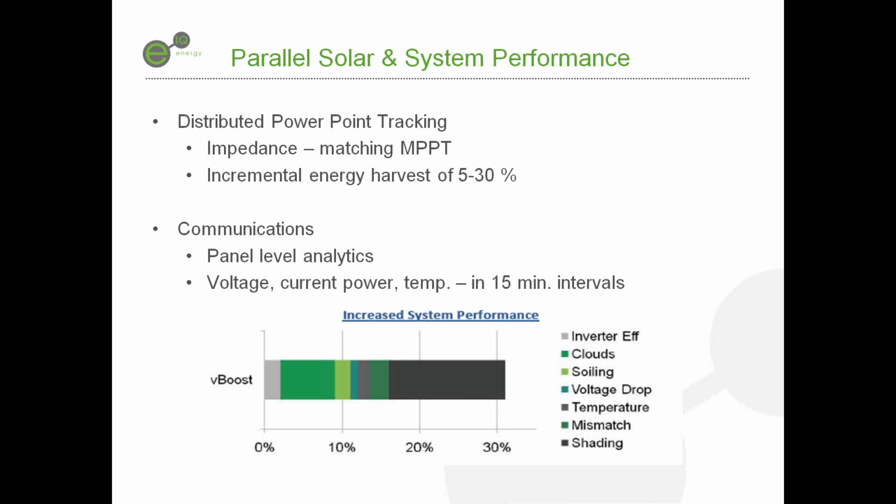And by doing this, you can see here that we're going to get a number of factors that build together in order to get the increased production story. So, for example, there's a couple of points available for inverter efficiency. And what we talk about by that is being able to drive the inverter at a consistent voltage that is right within that inverter's peak efficiency range. Once again, the inverter controls the bus, so you could simply set that inverter to whatever voltage it's most happy at, and it'll just sit there all day long.